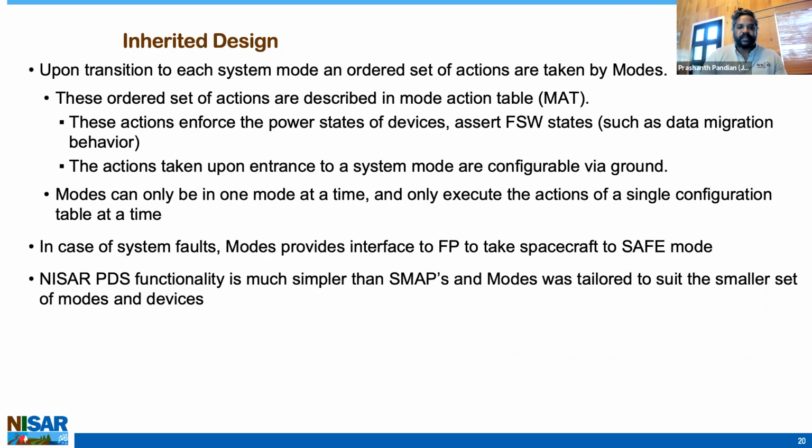Some of the things that made it easier for us in the modes engine: between each mode transition is a mode action table. This mode action table enforces the power states of devices and asserts various flight software states. We were able to implement all these things purely by updating the Statechart UML diagram. Next slide, please.